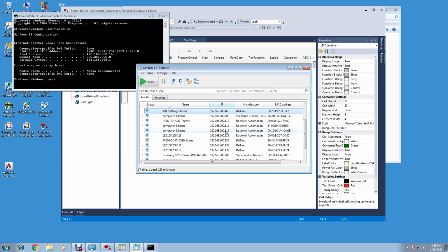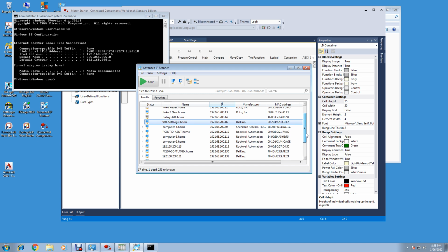I keep this for my IO and my frequency drives. So we need a space that's clear where we can get about 6 addresses. If we start at 100 and then go 101, 102, 103, and 104 for our network cards, we'll be in good shape.